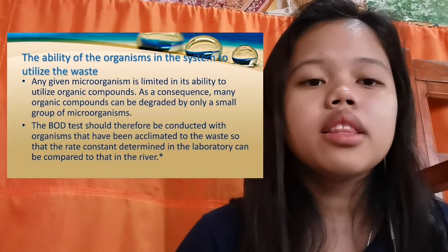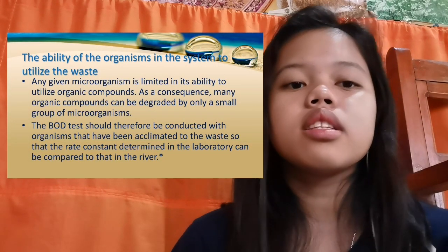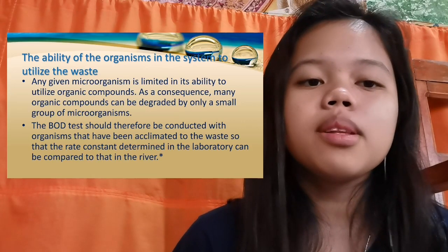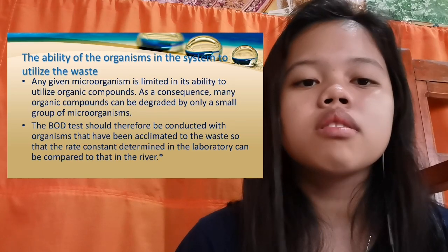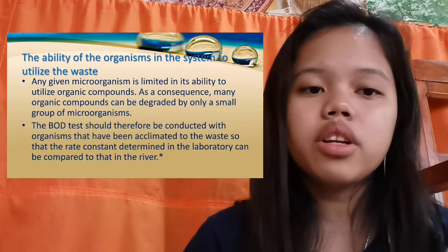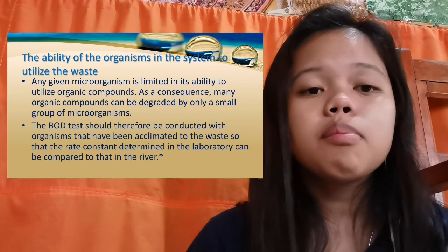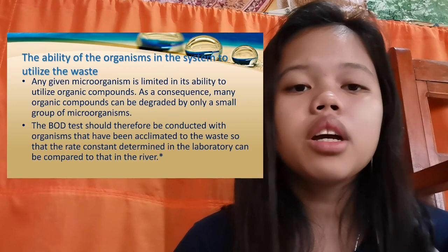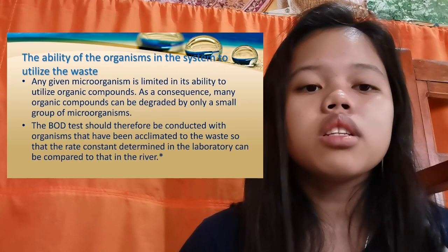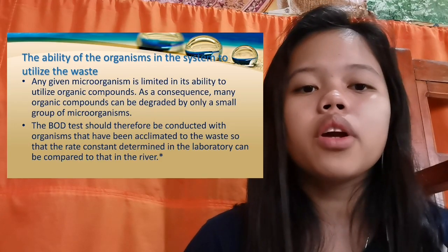The ability of the microorganisms in the system to utilize the waste. Any given microorganism is limited in its ability to utilize organic compounds. As a consequence, many organic compounds can be degraded by only a small group of microorganisms. The BOD test should therefore be conducted with organisms that have been acclimated to the waste, so that the rate constant determined in the laboratory can be compared to that in the river.